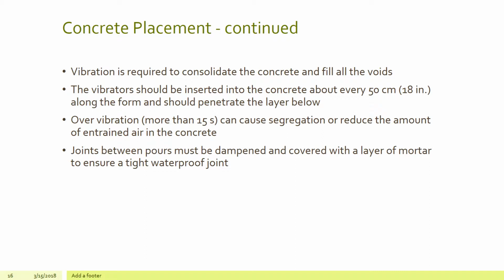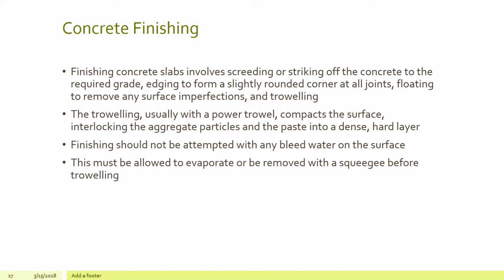Joints between pours must be dampened and covered with a layer of mortar to ensure a tight, waterproof joint. Let's take a look at concrete finishing.